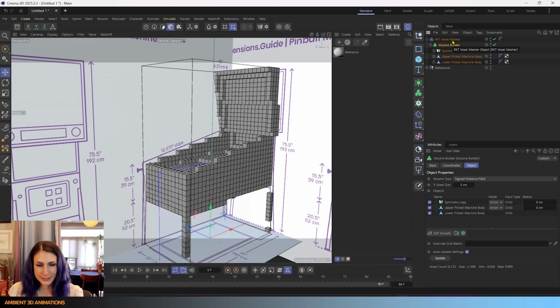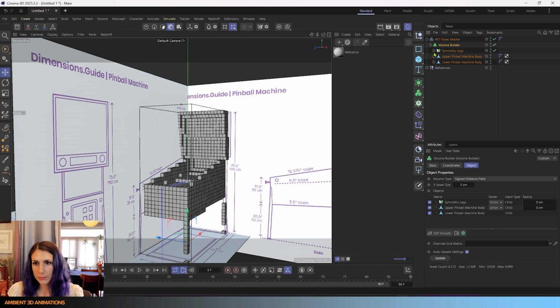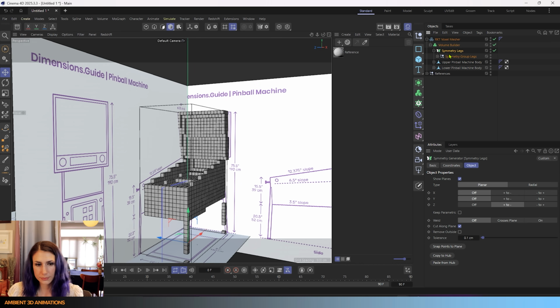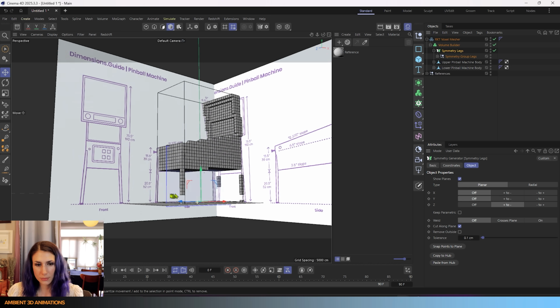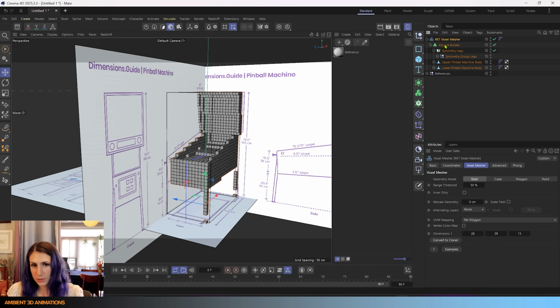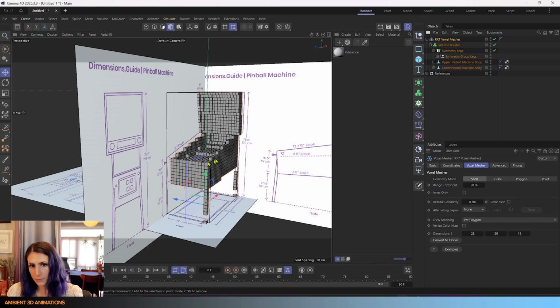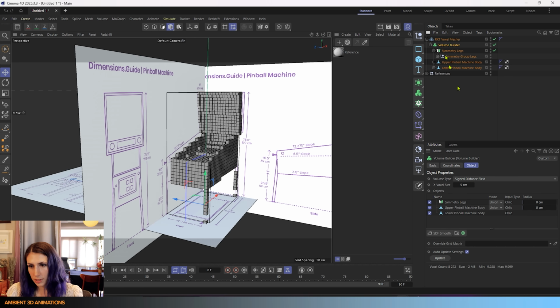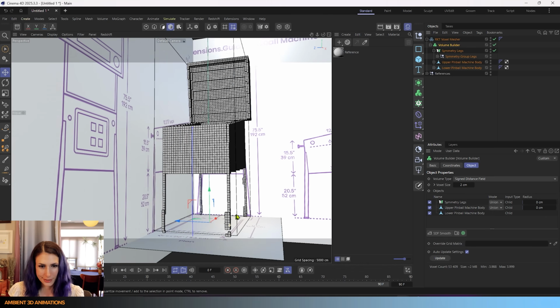So now it looks cool and pixelated. I like that. You'll see that it's having a little bit of trouble with this guy here. So that could be partially because they're so thin. So there's a few different ways we could probably problem solve that. We could make our voxels even smaller. So maybe we'll try 2. Oh, there we go. We got legs kind of appearing.